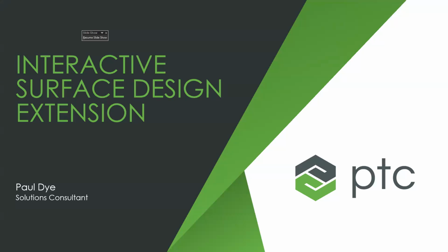And what PTC did was they incorporated that direct modeling kernel from Co-Create onto the Granite kernel, which allows you to have this freestyle capability of being able to take a primitive shape and create these complex surfaces and ideas while in a parametric setting, but not having to add the parametric intelligence up front. So it allows you to create things a lot quicker. So that's the reason why things like Freestyle and the flexible modeling extension exist in the base license of Creo.